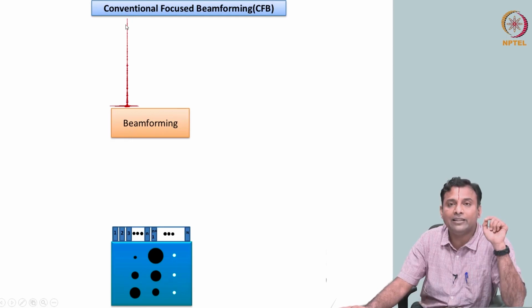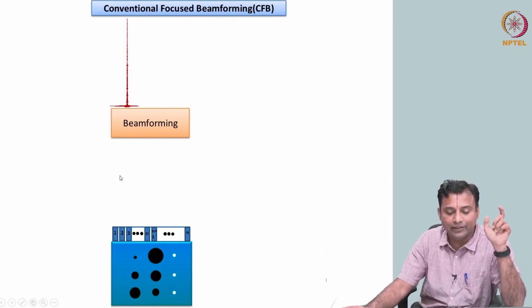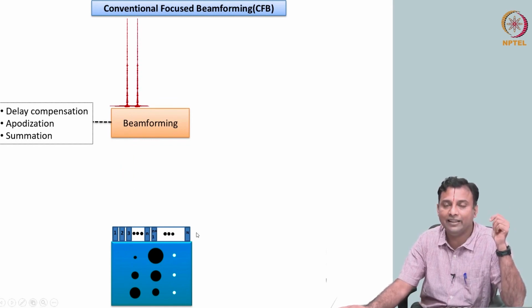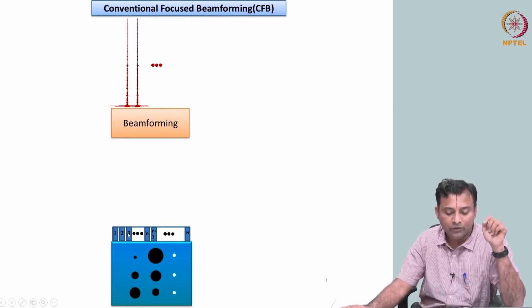I have one A line trace, this is called a post-beamformed A line. Okay. So I have only one line, how do I get an image? I repeat the process. Now I will translate the aperture, elements 2 to n plus 1, do the same process, and get the next line. So this is my scanning. I am not moving physically, but my electronics is translating the active aperture. So this is electronic translation, or electronic steering if you want to call it. Mechanically we are not doing it. You can do this so on and so forth till you reach the end.